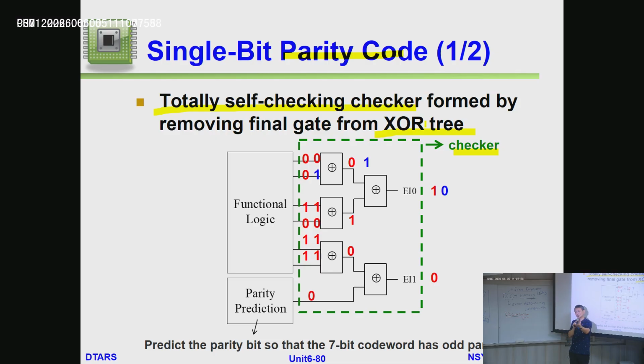But if you have more check bits, then it is possible you can correct the errors. So how many bits you need determines your cost, right? Because originally you just need 6 bits in your system. When you write RTL code, you only need a 6-bit output. Now you need 7 bits, so you will have more interconnection.